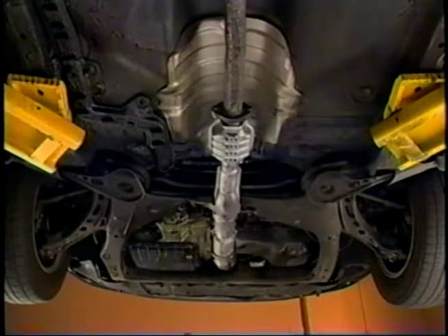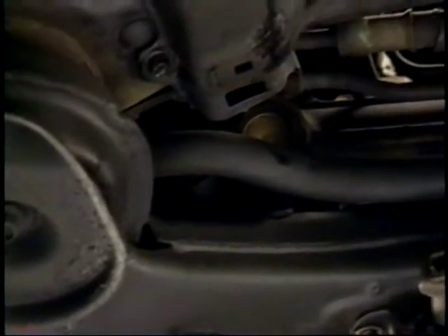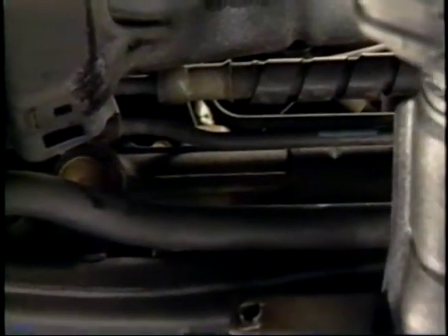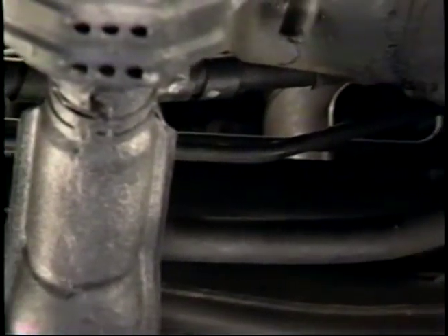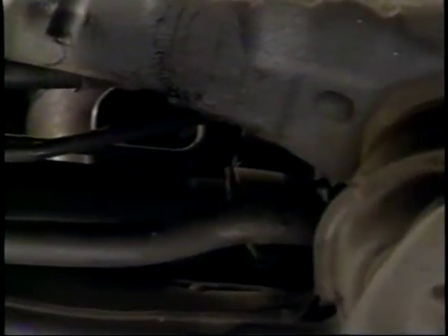Rack and pinion systems differ from traditional steering gears in that they don't use the elaborate linkage systems that traditional steering gear systems use to turn the wheels. To diagnose a rack and pinion problem, start with an inspection of the rack and pinion steering unit. Check for loose or worn mounts that can cause the rack to move or vibrate. If the mounts and rack alignment are okay, the problem can be inside the rack and pinion assembly.